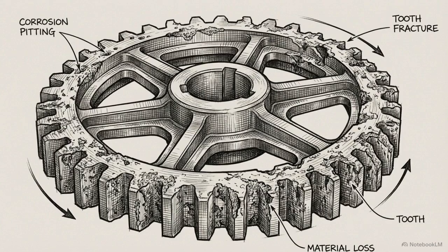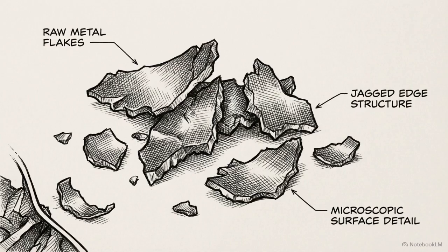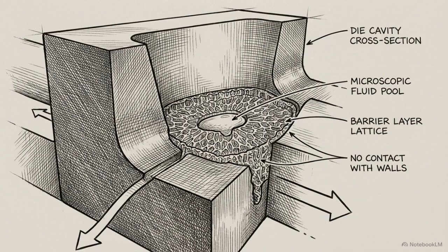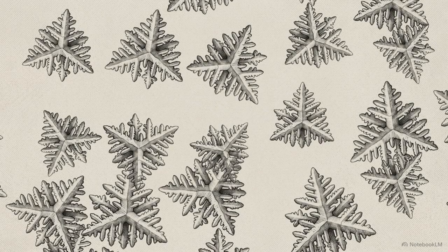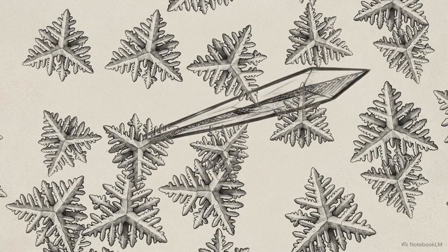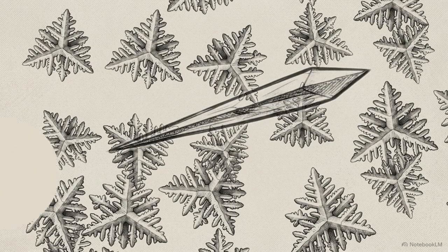Increasing the raw load capacity of the casting inevitably sacrifices its environmental durability and castability. Unlike copper or magnesium, iron is technically an impurity, yet a specific amount of iron is deliberately tolerated because it chemically prevents the molten aluminum from soldering to the steel die during injection. Left uncontrolled, iron adopts a disastrous physical morphology, the beta iron phase. It crystallizes into sharp, invasive, needle-like plates that pierce directly through the ductile alpha aluminum matrix.